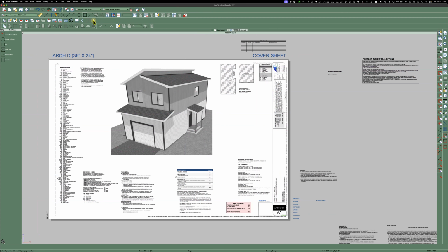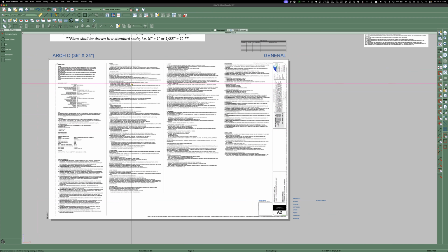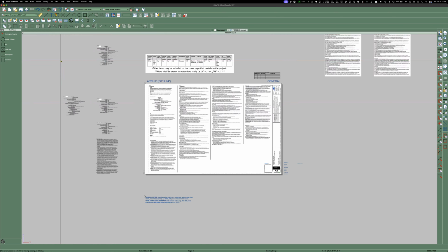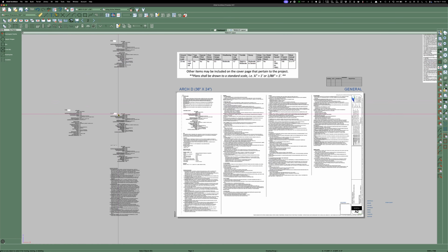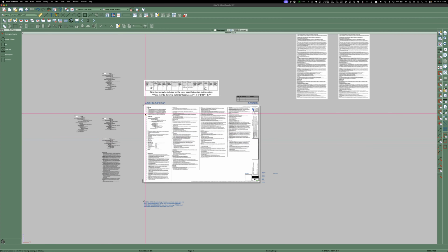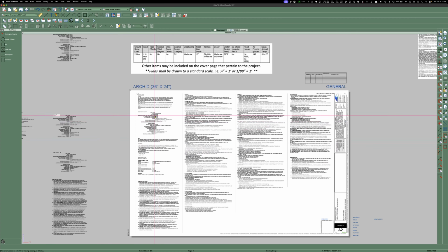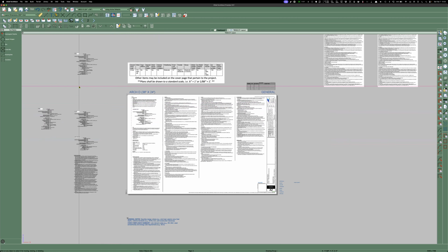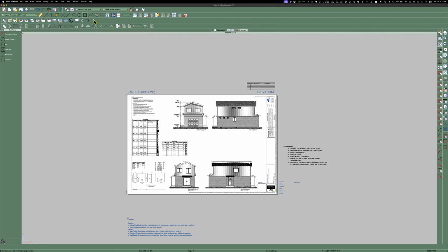Okay. Bunch of language here. This is your standard building language, little requirements and stuff. And if you'll notice, I have different counties over here. Kitsap, Clallam, there's another Kitsap. That's actually in Oregon. But this one's going to be in Snohomish. And they're all a little bit different. Some of them have a different snow load or a different seismic. And so you want to make sure you get the right one for the right location.